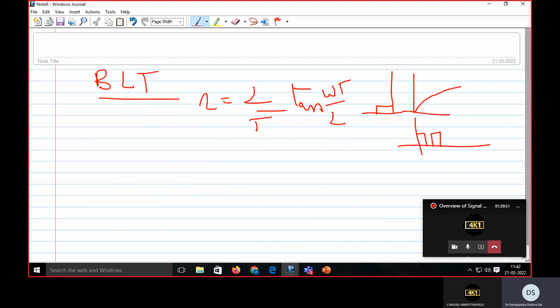But why is it becoming nonlinear? When designing impulse invariant, we didn't talk about nonlinearity. Why? Because we are considering only low frequencies. For low frequencies, it is linear only. As the frequency increases, it becomes nonlinear. Because of that, this problem is seen in bilinear transformation only. You don't have this in impulse invariant. It is linear only, because we are discussing only low frequencies.